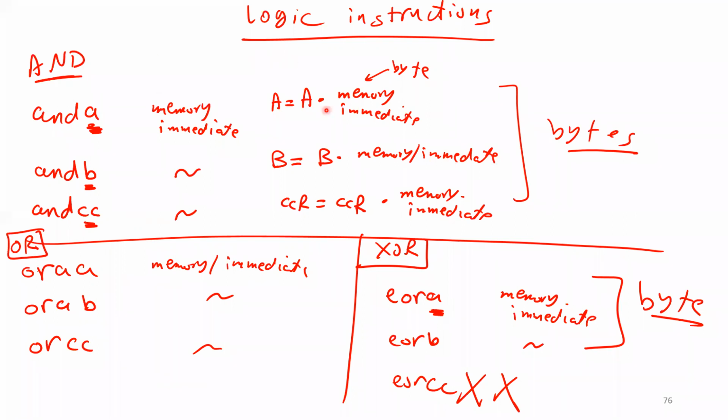If you have register D, I can do AND for A and for B, right? So if I can use these two instructions, this means I can do a 16-bit AND with register D, right? But we don't have one instruction for logic AND. Okay, guys. That's all we have for AND.